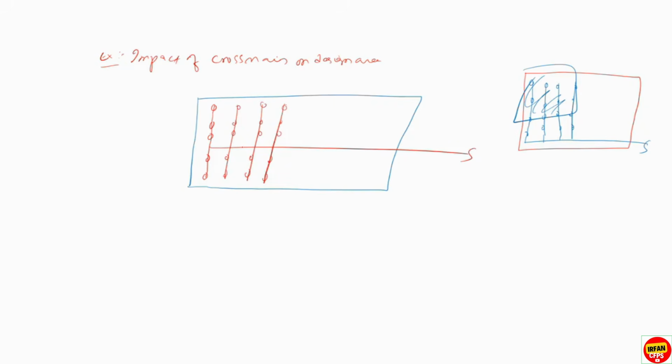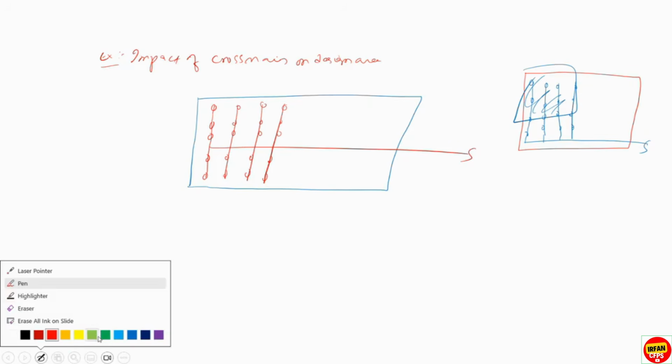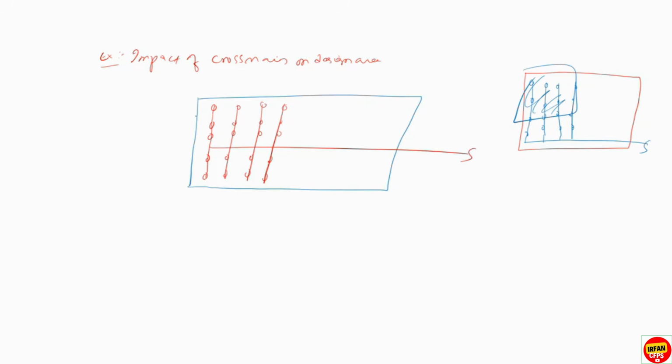The procedure is simple and the same, but here most designers will make a mistake. They will select this entire area, for example 46.47, and all these sprinklers because these are the remotest sprinklers from the pump.